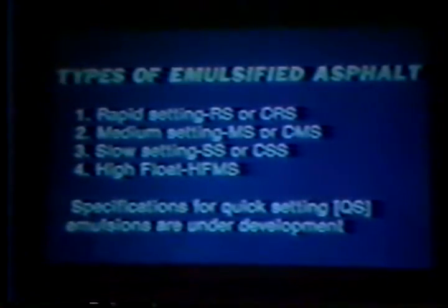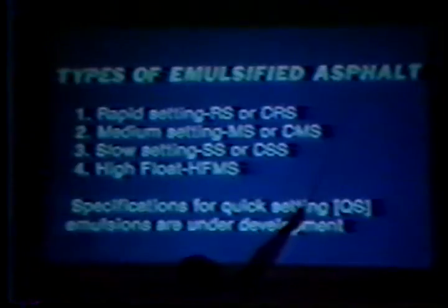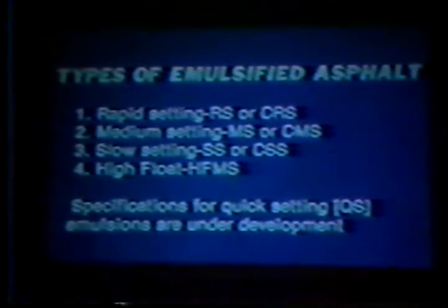And there is one more fluke, as I say here, because of the proprietary activity in emulsions. This has been identified recently by AASHTO and others, and we have to acknowledge it too. But it's really nothing more, and I kind of wish they had put it up here in parenthesis next to a medium set. It's a product called high float medium set emulsions. And the only difference is that when they run a test on the asphalt cement that's used, there are different properties that are measured. The proponents of the product claim different kinds of virtues of performance with it, and we always have to defer those claims naturally to their own documentation.